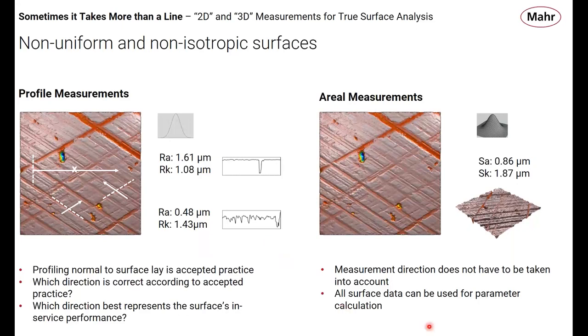The big advantage to aerial, specifically for surfaces like this, is we can force ourselves to catch all of the data. That SA parameter represents all of the hone marks, even the pits that are in the surface. Again, there's another webinar there. If Mark Malberg were here, he would probably have some words for me on this topic. But the idea is if we can use this SA to capture all of the data in that surface that represents our roughness. So that's a big point here.